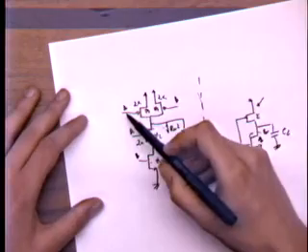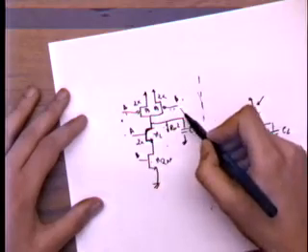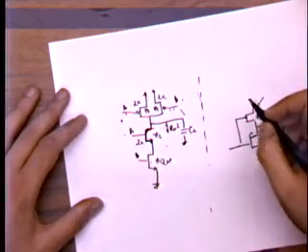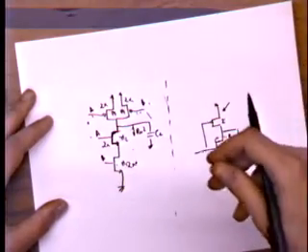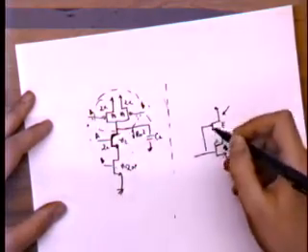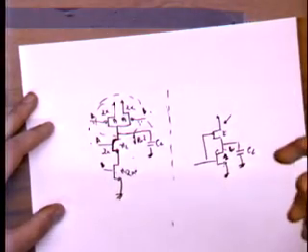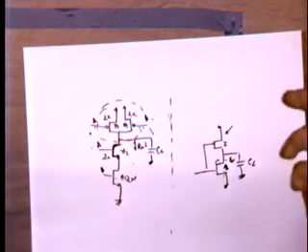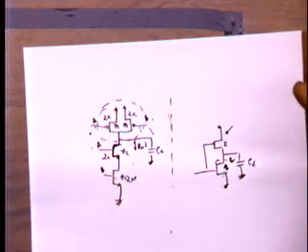So that in case A goes low and B stays high, or A stays high and B goes low, we are going to have the same pull-up strength as a standard inverter. But there is still going to be the case where both A and B go down at the same time. And in this case, we're going to have a pull-up strength that is both of these devices. And therefore, it's going to be twice as strong as the inverter. And therefore, in this particular fortunate condition, we are going to have a delay which is roughly half that of our reference inverter. However, this is not useful because we don't know if we get the worst case delay or the best case delay. And therefore, we always need to design for the worst case delay. Okay?